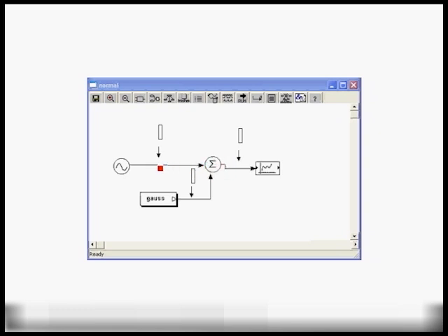and the buffers never overflow in this case, and you have a nice smooth simulation, in which case the add block basically receives 128 samples, adds all the 128 samples to each other and outputs them to the output buffer, and the plot block basically collects those samples in order to eventually plot all million samples, for example.